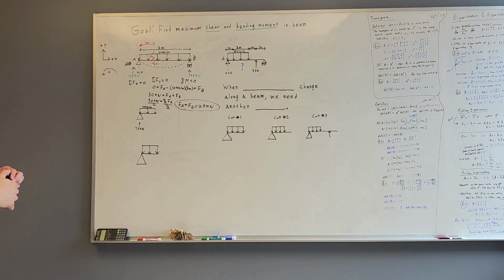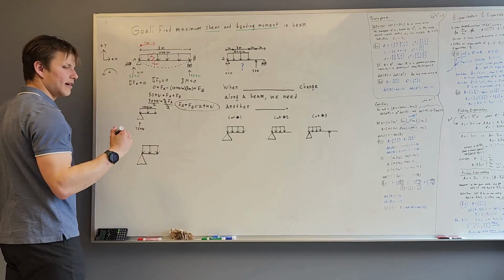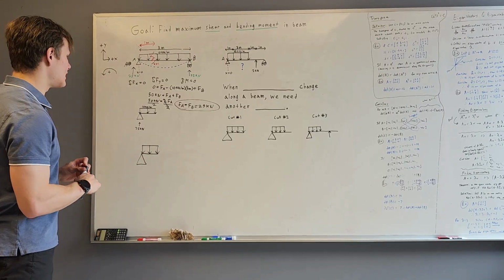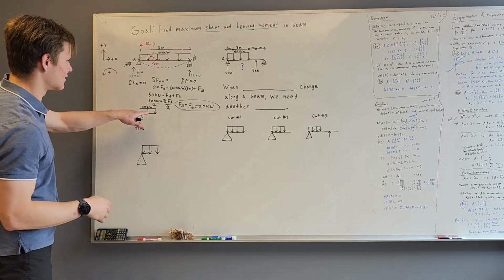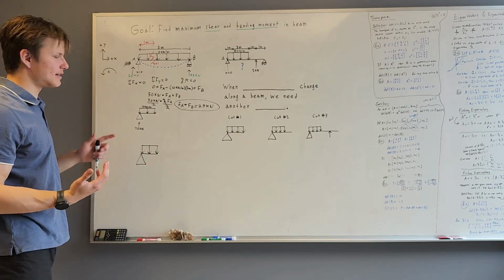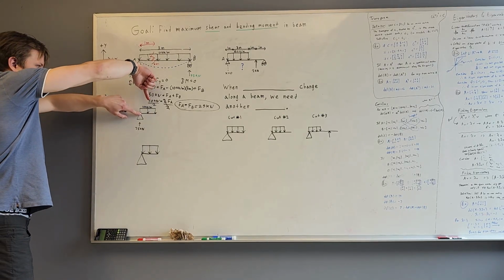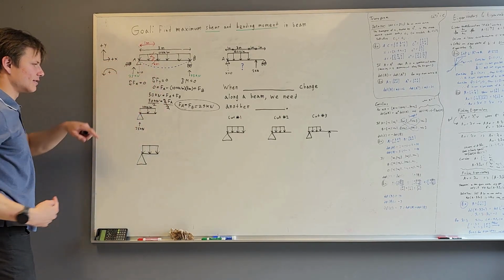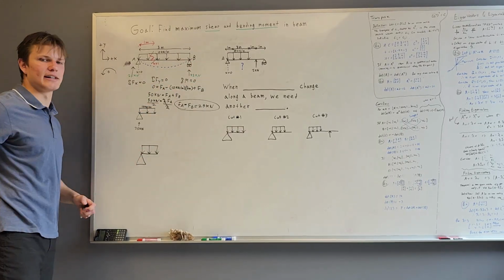But now, this right here is not balanced, and we know that because right now this pin is the only support supporting this load right here. If this were to happen in real life, this is a pin right here, and this beam would just rotate down like that because there's nothing to resist that moment. We've lost our support over here.